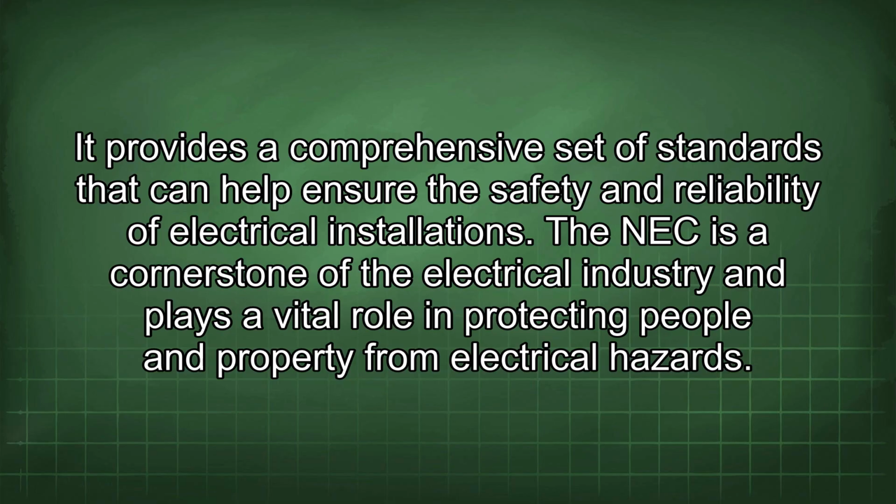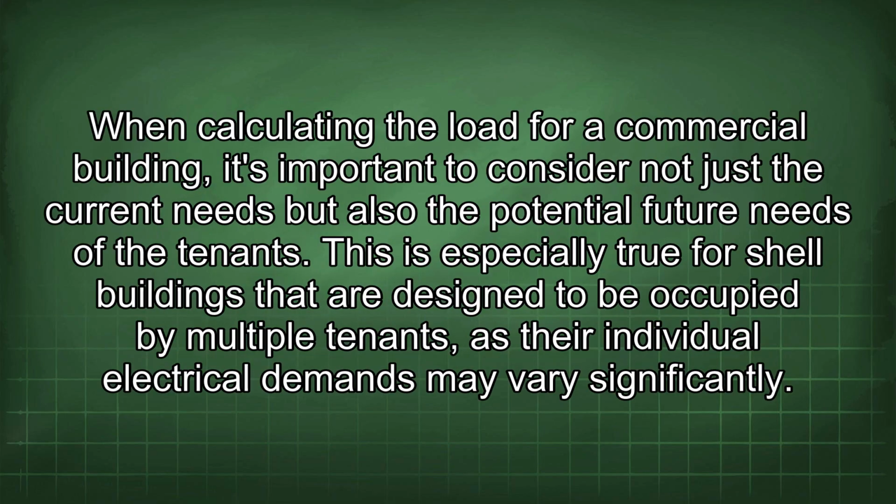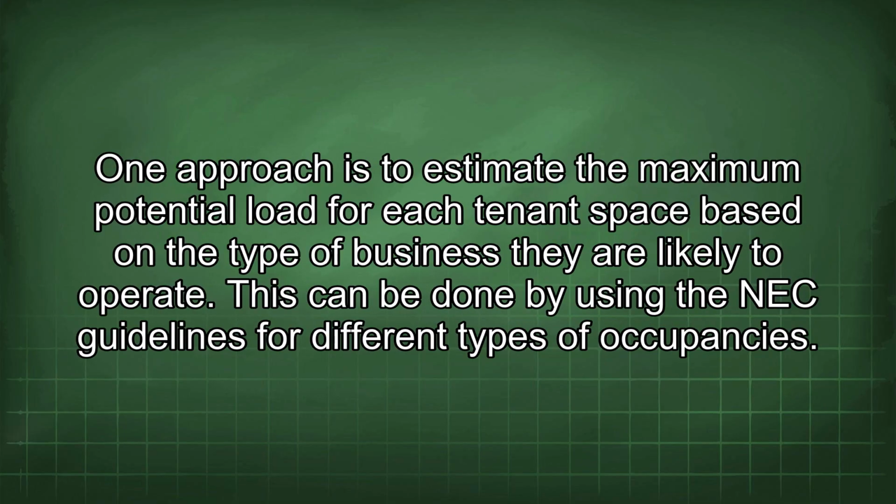When calculating the load for a commercial building, it's important to consider not just the current needs but also the potential future needs of the tenants. This is especially true for shell buildings that are designed to be occupied by multiple tenants, as their individual electrical demands may vary significantly. One approach is to estimate the maximum potential load for each tenant space based on the type of business they are likely to operate.